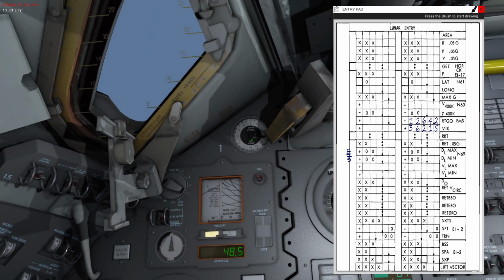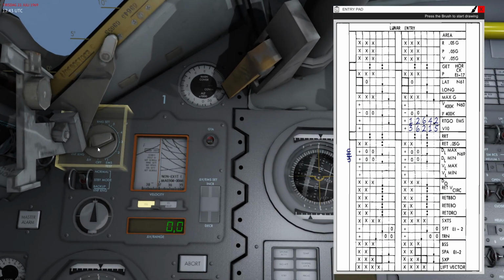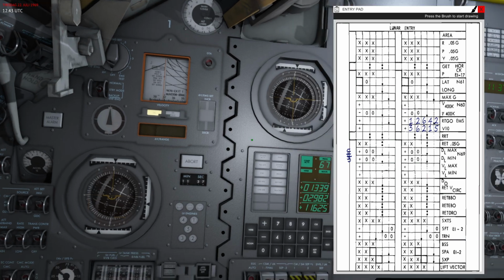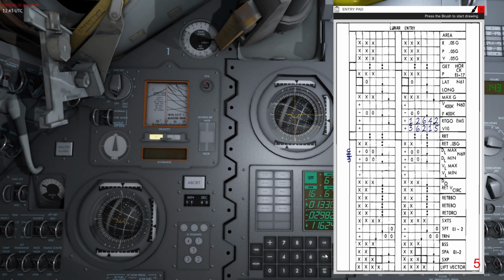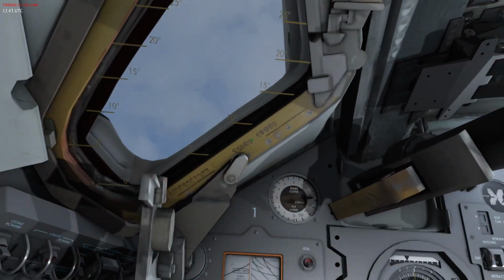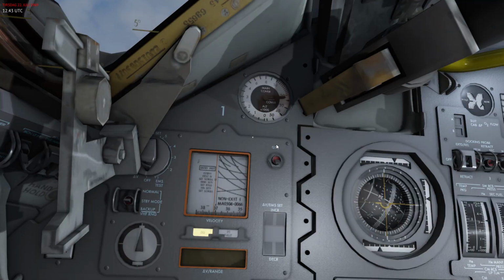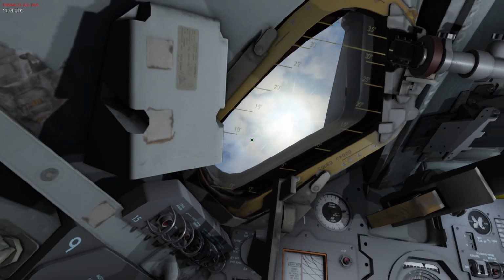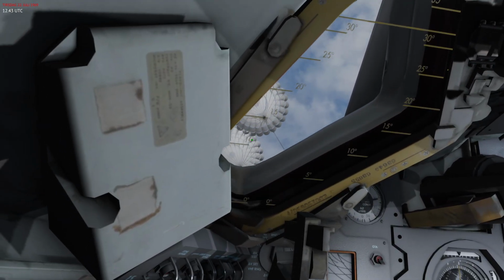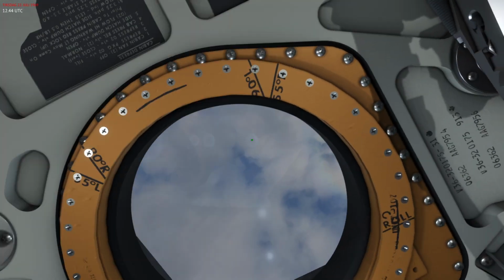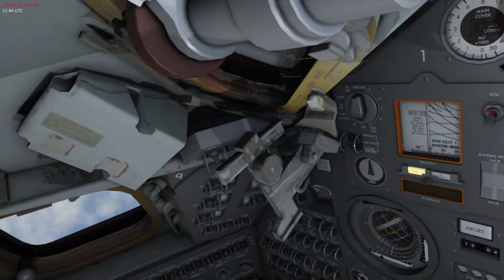And now I'm closing down to the drogue chute altitude, so then I can set the EMS modes all to standby and off. Right, there come the drogues. It's always good to visually see the drogues as well.